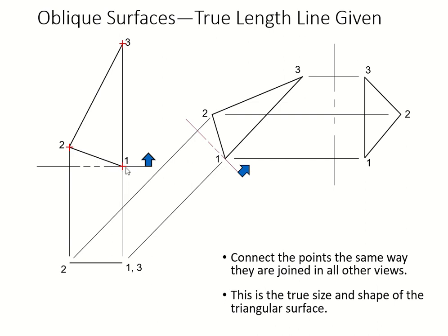1 and 3 have to keep this distance, 2 and 3 have to keep that distance, and 1 and 2 have to keep this distance. So how do we come up with that? Because of how we place our second fold line at the edge of our middle view, see? Since we put the edge, we're going to throw this fold line, and we're going to start from point 1 like this.